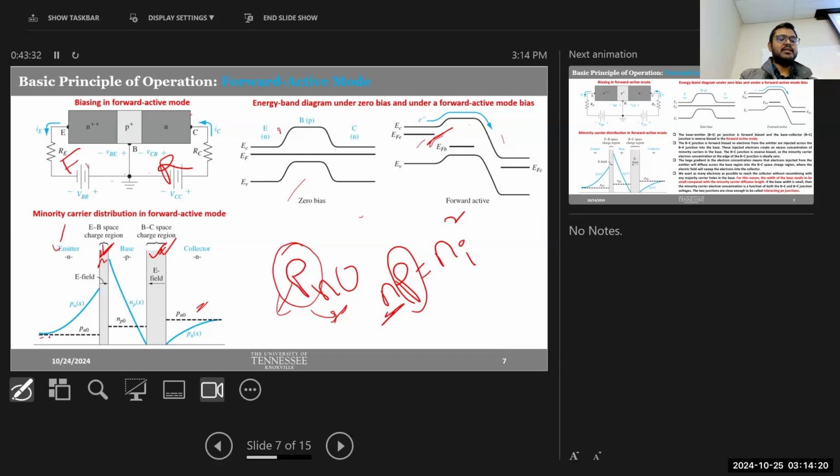That's what we see, these three dashed lines are the equilibrium condition. You see that on the emitter side, we have the lowest amount of holes, right? Now, if we go to the base region, which is P-type, here we'll have more holes, but the minority carrier will be electrons. That's why you see this notation here, the number of electrons. On the P side, 0 means the equilibrium, okay? So here you can see the concentration of electrons in the equilibrium condition.